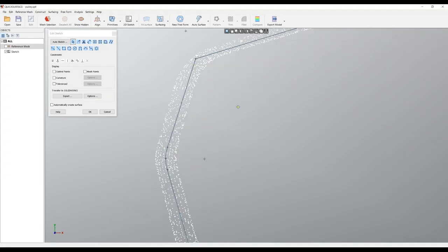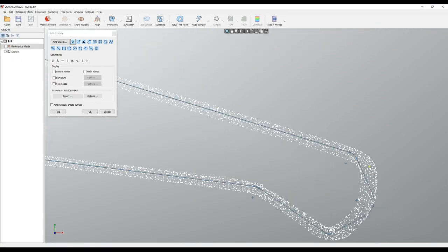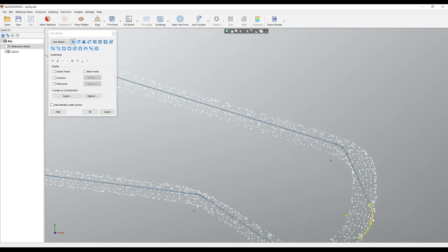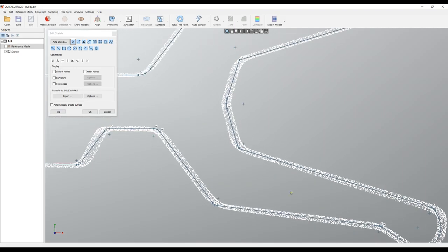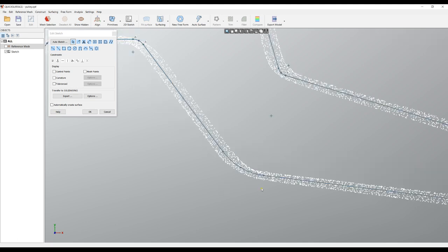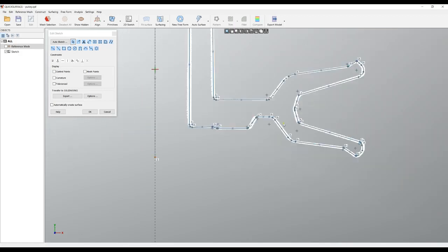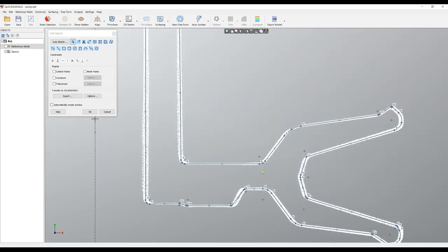Why I show this is that this wizard style helps you reconstruct these features, but it doesn't stop you after that from continuing to modify them until you achieve your desired results. For example, here I can improve my fillet, I can create dimensions, I can give values to these fillets until I get what I want as a profile.